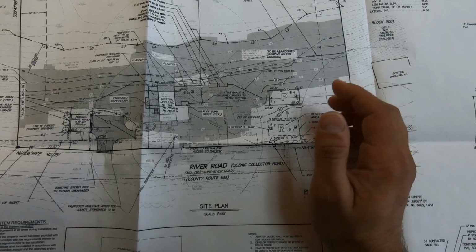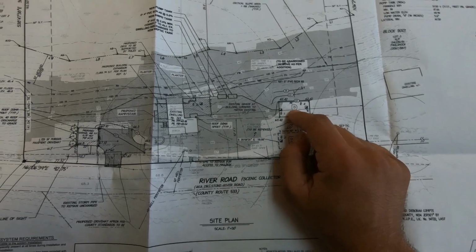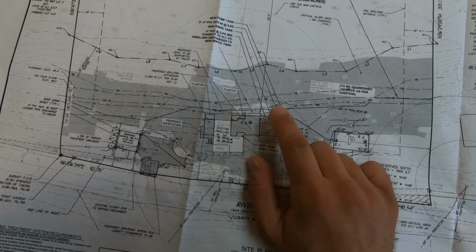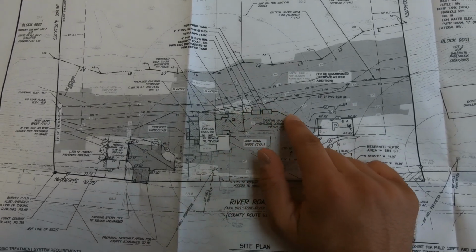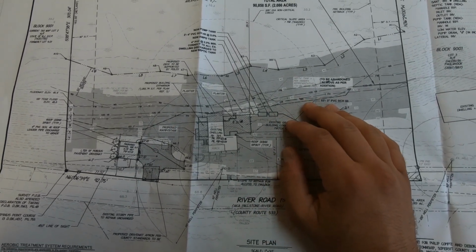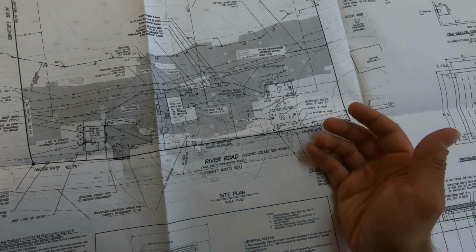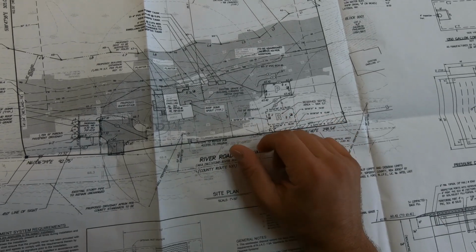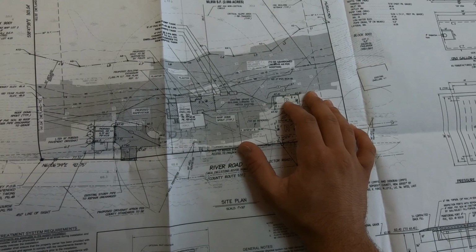You're also going to want to do the same for the deep inspection port that's part of the septic field, and you're going to want to do it for the manhole for the pump tank, the manhole for the septic tank, and occasionally if there are cleanouts along the line, sometimes you'll want to nail down where the location is for that. That's just so that in a future inspection, all of these components can be located, and we can confirm that it was built in accordance with the plan in the proper location.